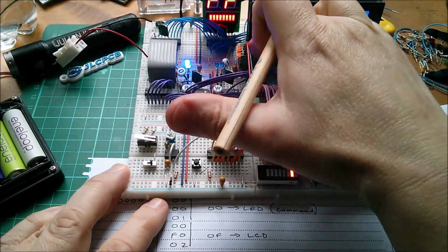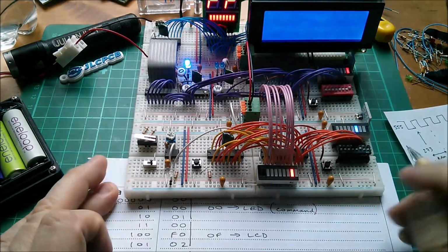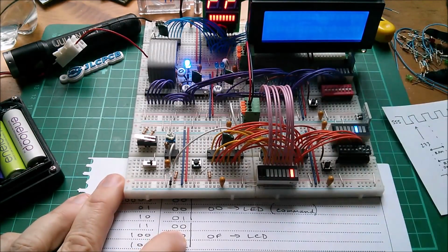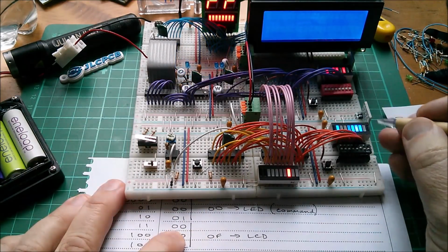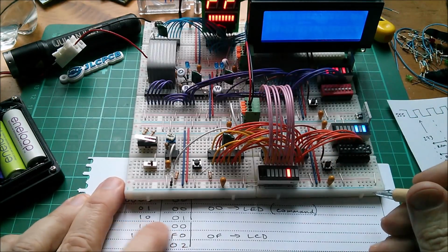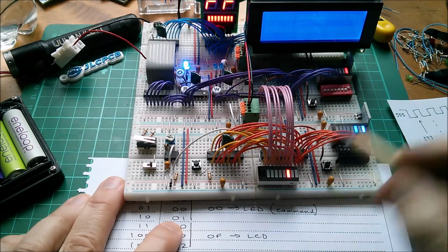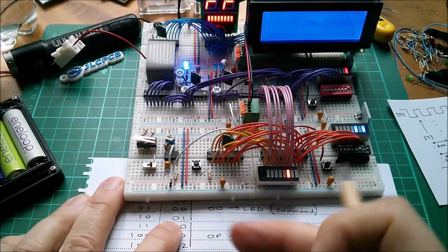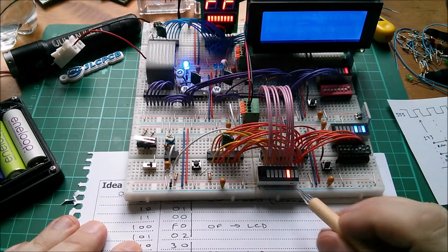How is my power distribution holding out? Obviously not brilliantly. So 3 goes to 4, and on step 3 it's 00. Oh, it's all flickering a bit. Never mind, let's plow on. Next, 4 goes to 5, quite obviously, and in step 4 we've got 01. So I'm programming the go-tos and the data together. Sometimes I go through and do all the go-tos and then go back and do all the data for each location, but I just thought I'd do it this way this time.